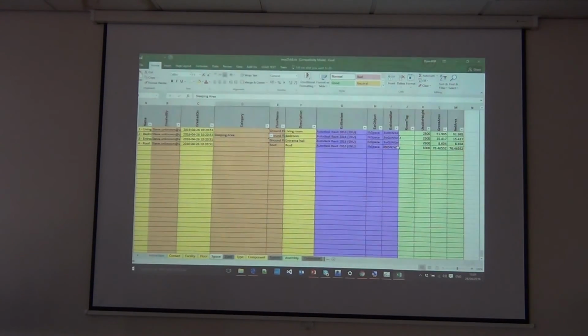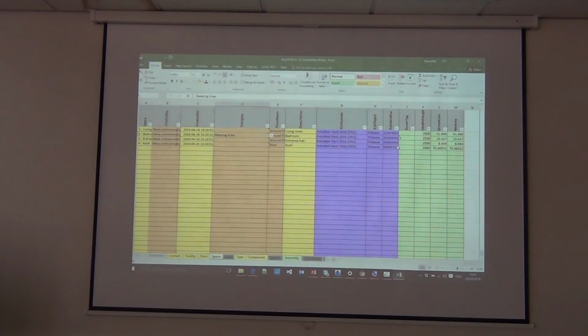The problem is, at the moment, not many people understand how to do this, so they go off and do everything afterwards. So what they commonly do is run the Revit Cobie exporter and send it, because all they've been asked to do is get Cobie, and I'll show you what happens when I do that.